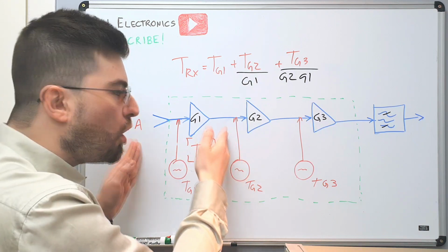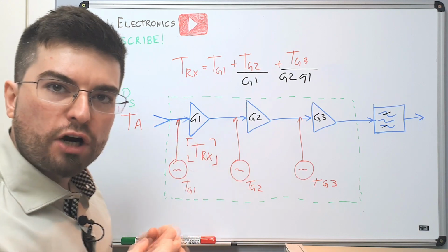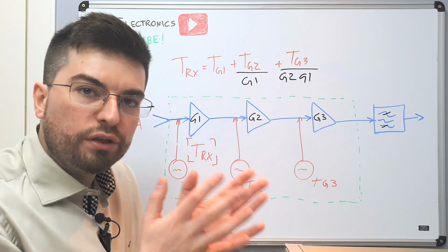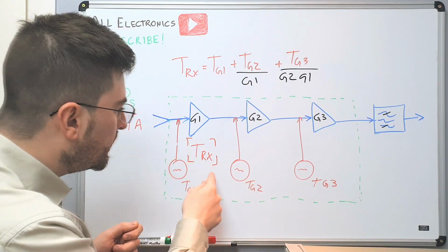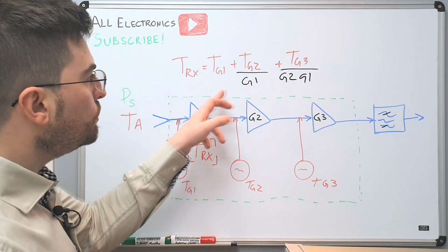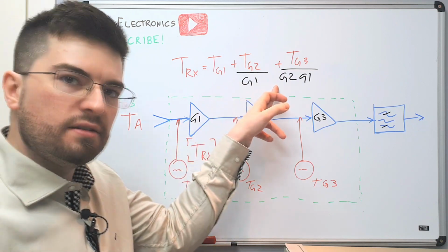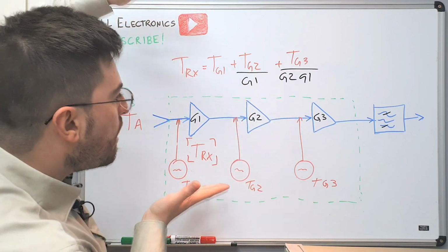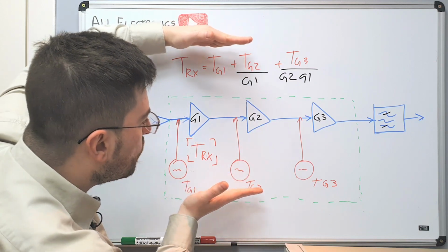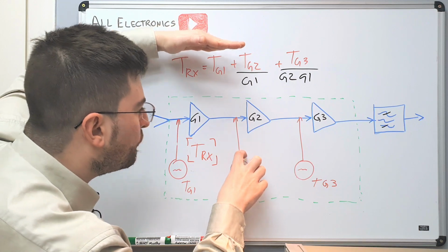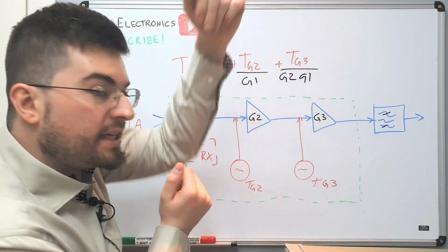The first block is responsible for amplifying the signal without degrading too much the signal to noise ratio. All the blocks that follow can have a much looser constraint on the noise temperature because the signal is already amplified and it is larger in comparison to the small amount of noise that is added in each step.